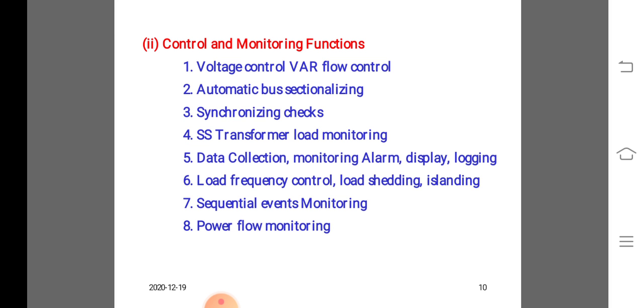Improvements over twisted pair wire came in the form of what is now the most common traditional type of telemetry mediums, based on leased wire, power line carrier or microwave. These are voice grade forms of telemetry, meaning they represent communication channels suitable for the transmission of speech, either digital or analog, generally with a frequency range of about 300 to 3000 Hz.